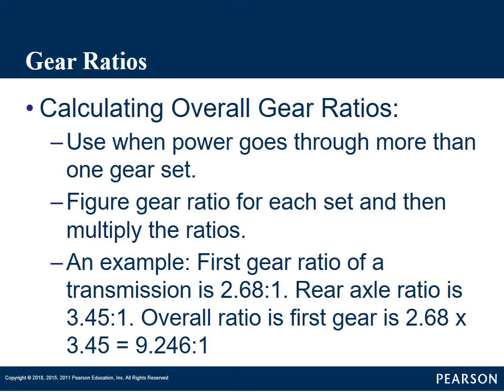Now that we know how to figure individual gear ratios, like for first or second or third, or if you're talking about a differential, we can also figure overall gear ratios, because we'll have gear ratios in a transmission, and then we have a gear ratio in our differential. Even if we're talking about a transaxle that has the final drive, the differential in the transmission, it has a separate gear ratio than our transmission.